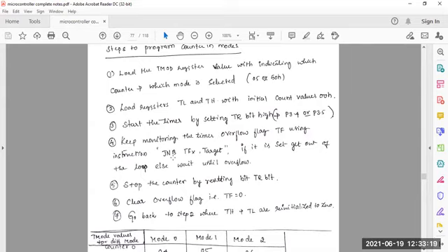Till the TF value becomes 1, it will keep on counting. After JNB TF, when TF equals 1, we stop the counter by making the TR bit equal to 0. Previously we set bit TR0; here you have to use the instruction CLR TR0.